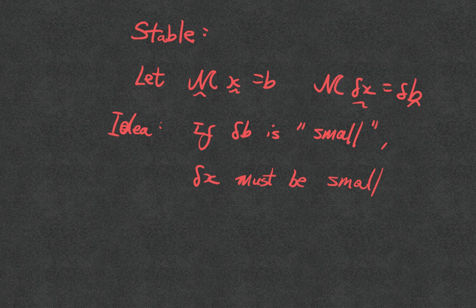Now, why do I hate those non-trivial null spaces? Not that I hate them, but I just don't want them to exist. There's a very important difference between the two. If you have those null spaces, can you still control x? You cannot, because I can put any alpha times that null vector there, and it will still be the same system.